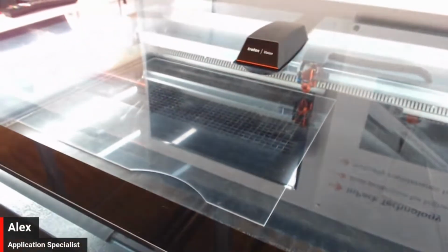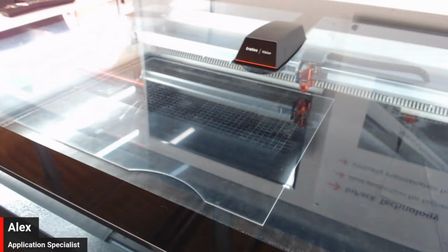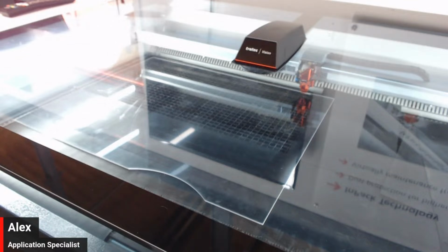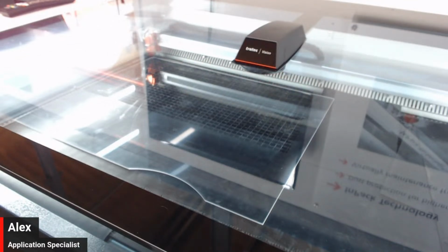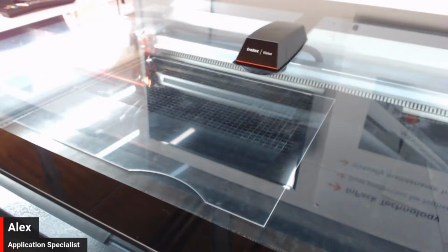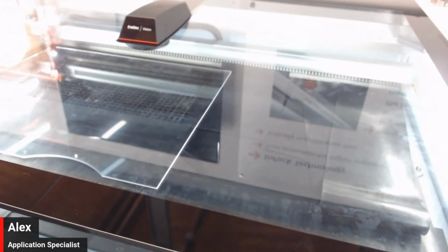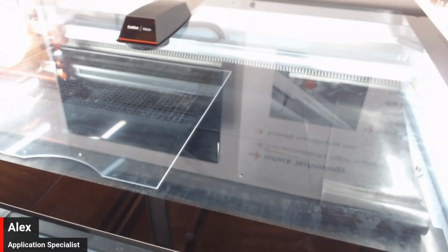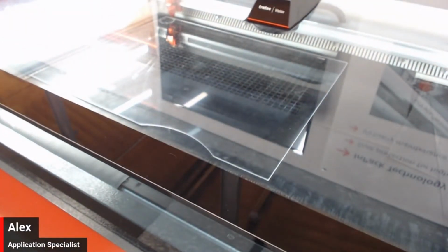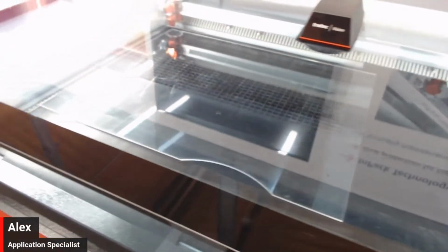So I'm just going to hit start on here, and then we'll let the machine run away and get started on this job. We have a little delay for the extraction startup, and then away it will go and it will start working. So looking at this setting that was already on here, I can see there's quite a bit of flash when the laser is actually cutting. And to me, that means that there is a lot of excess power left. So you can see those bright sparks every time it cuts. So I'm just going to go straight into doing it.